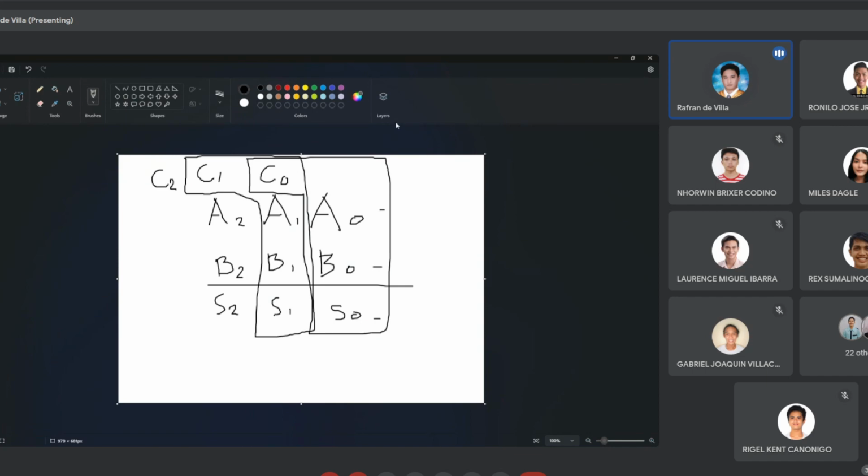So, you have here A1 plus B1 plus C0, which serves as the carry out from the previous bit position. Okay? So you have here your output S1 and another output, your carry 1. Okay? So do you get it, guys? Why the full adder has 3 inputs. So as you can see, with the full adder, you can replicate its circuit so that you'll now be adding 3-bit numbers. Okay, based here.